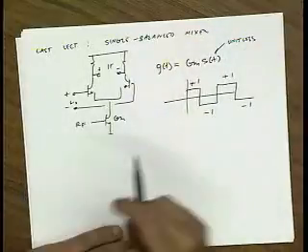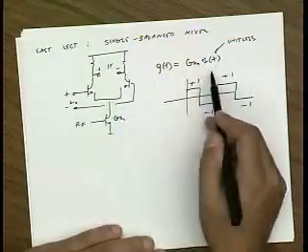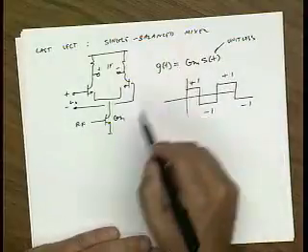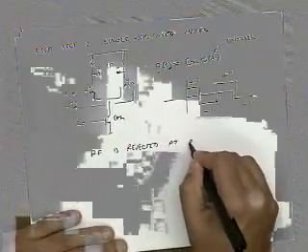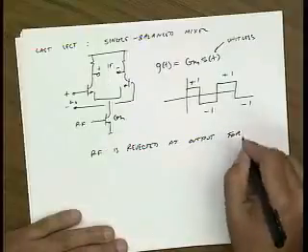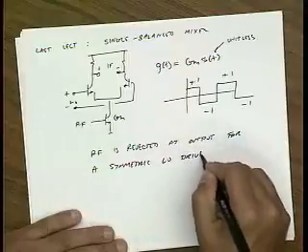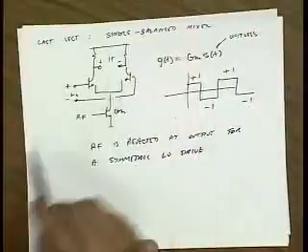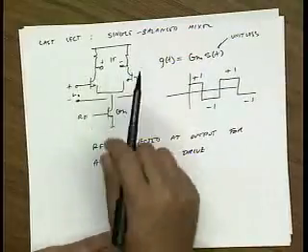Okay? So the nice thing now is that because this G of t doesn't have any DC value, when we multiply our RF by this G of t, there is no RF at the output. The RF is rejected, for a symmetric LO drive. As long as we can maintain this balance, we assume that this is a fully balanced circuit, we reject our RF. Okay? But we still have the LO leakage to the output.